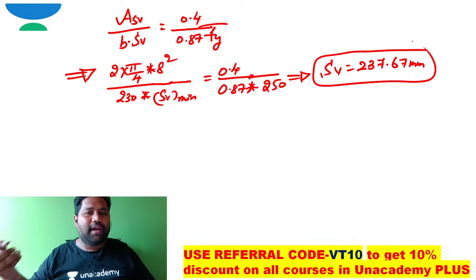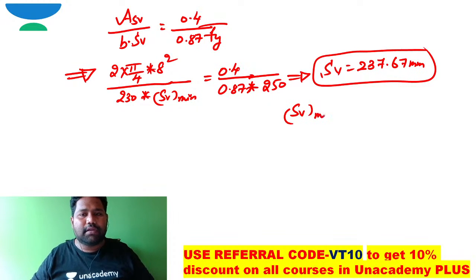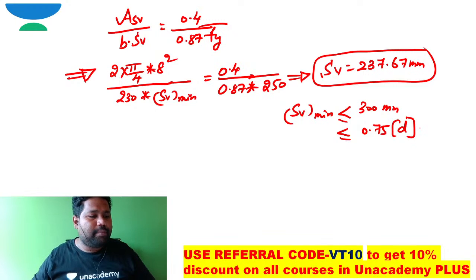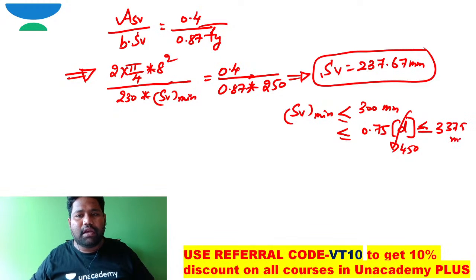But I cannot finally conclude this. This Sv minimum shear reinforcement should be less than 300 millimeter when using vertical stirrups, and should be less than or equal to 0.75 times d. In such case this should be less than or equal to 337.5 millimeter.